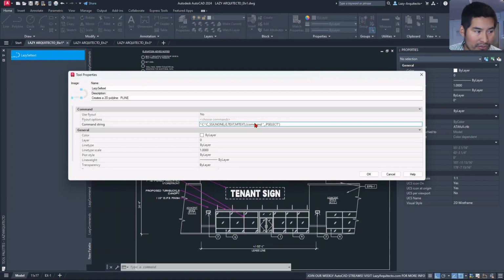All right. So once we utilize that command, AutoCAD is gonna ask us something, and what we're gonna respond, using these quotations again, is P for previous, and finally we're gonna press an enter by using these two quotations again. All right. So this is again an alternative for this person, and hopefully for other friends also.